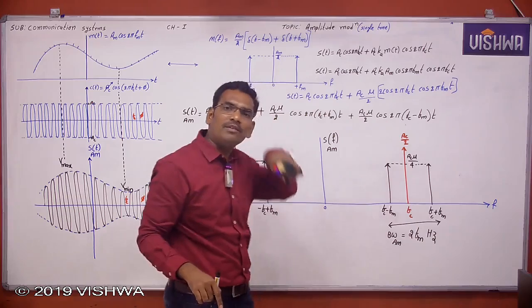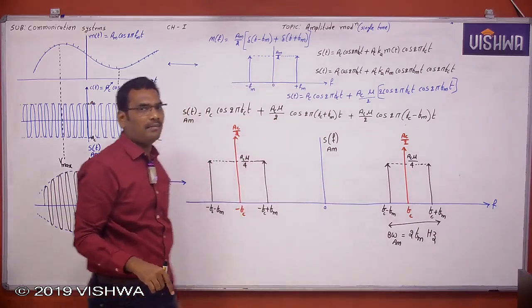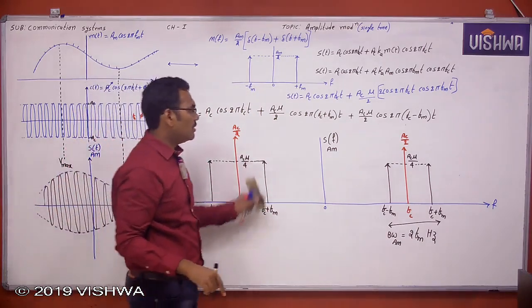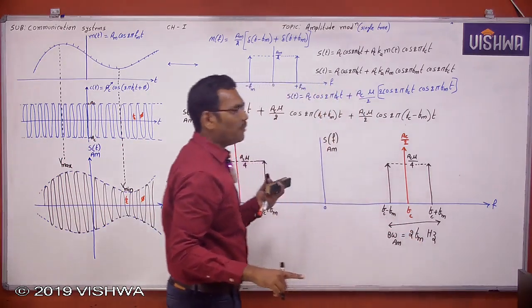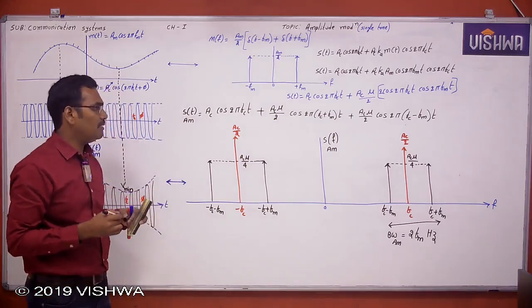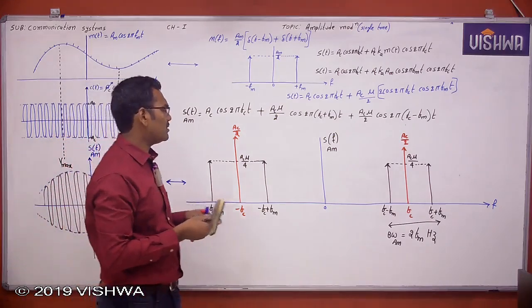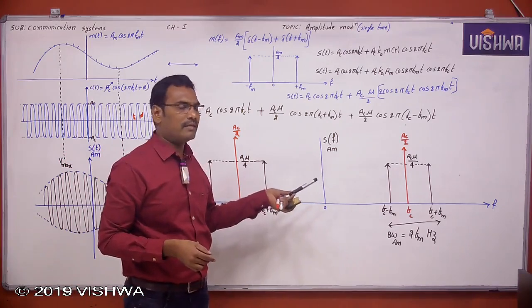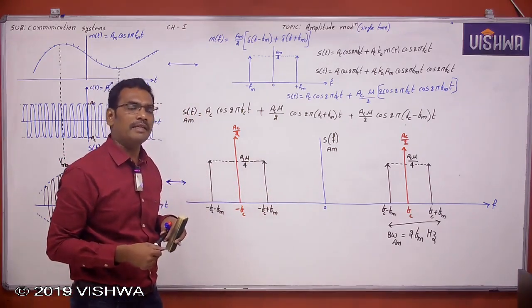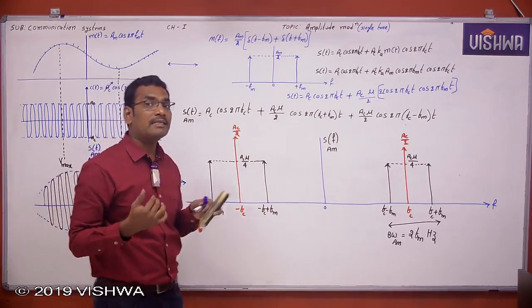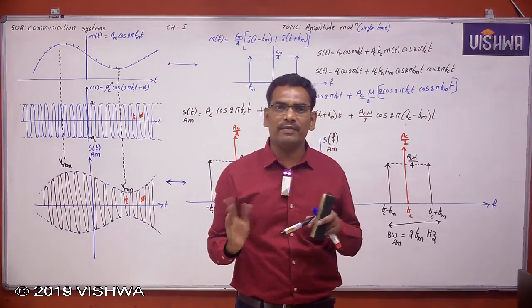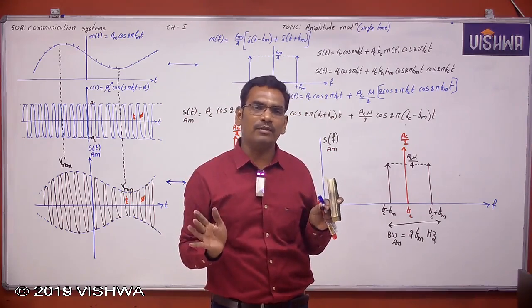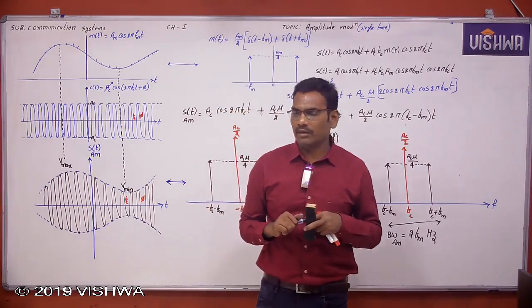If it is a multi-tone signal, that is 2 omega. Multi-tone means 2 omega hertz. Single tone means 2 fm. fm is the frequency of the message signal, but omega is the highest frequency present in the message signal. Now this is the single tone frequency spectrum, and the previous one is the multi-tone frequency spectrum, and this is the way we calculate the bandwidth. Okay, but there is no need to find bandwidth for single tone. If you find bandwidth for multi-tone, that will be final for everything. Okay, now note this.